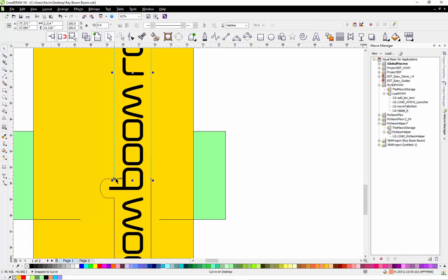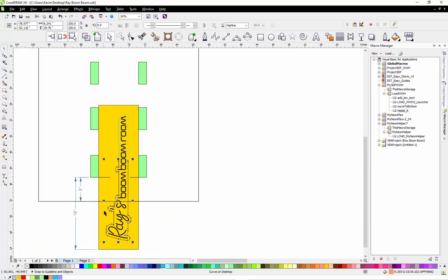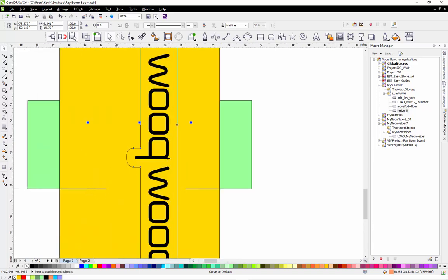And you can also see where this ends, and you can also see this one here. I'm going to bring it to the front. So there is 2 inches of overlap, is how I have it designed. So if we start the start position of the job at the same point on both halves, then the tool should start pocketing this right in place where it needs to be.